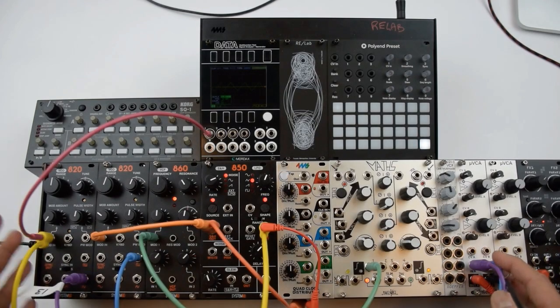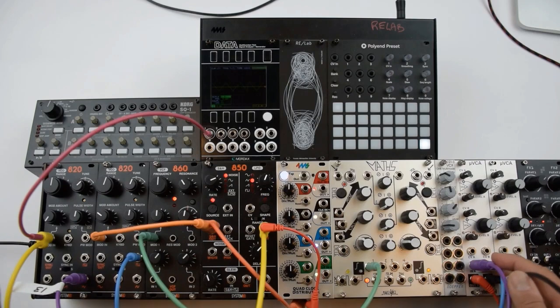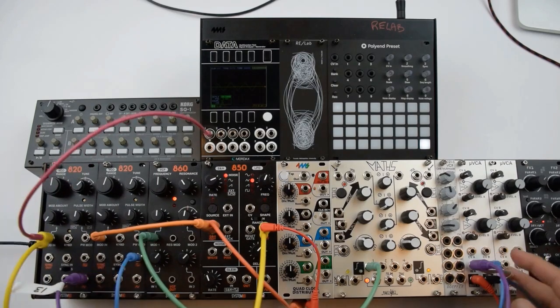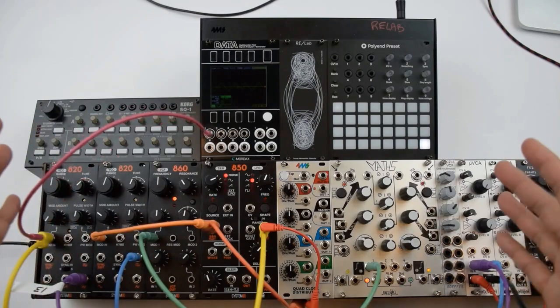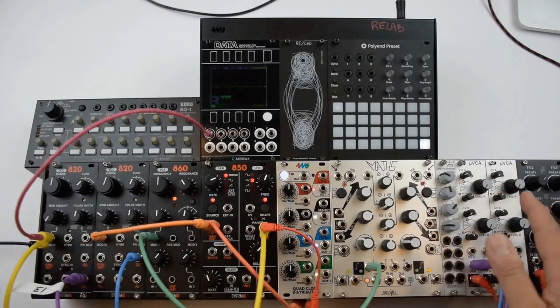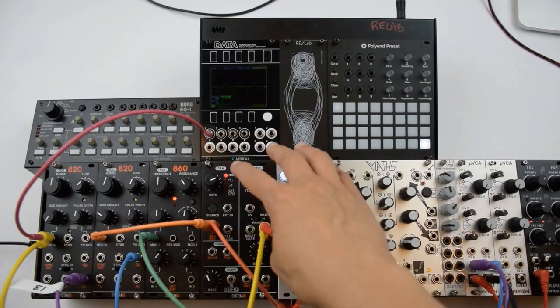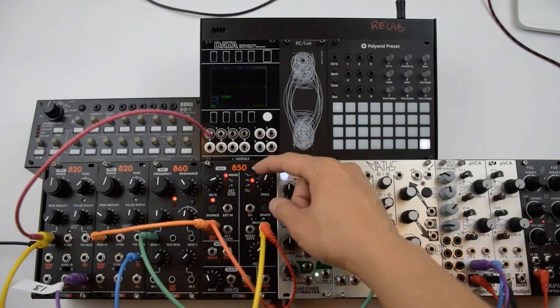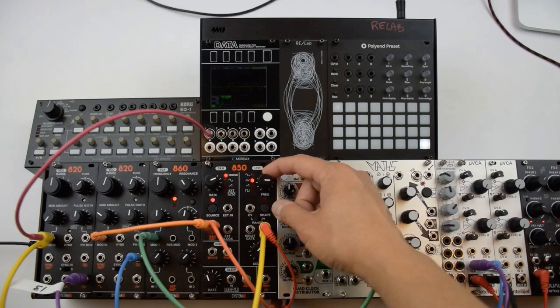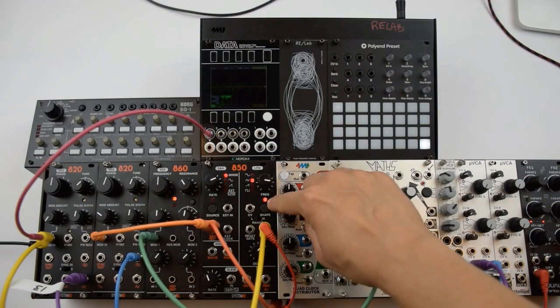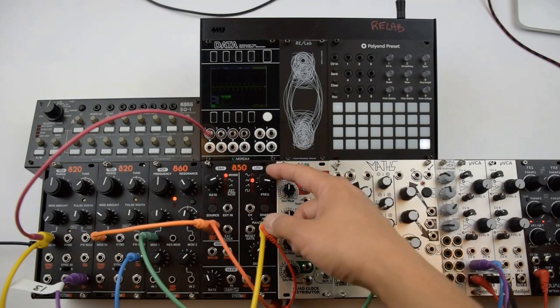An LFO, or a low-frequency oscillator, is simply an oscillator that runs very, very slow, below audio rate. So not at a frequency where we can perceive audible pitches. Everything we know about an oscillator still applies to the LFO, in terms of it outputting repeating waveforms and having those waveforms run at a steady rate set by a frequency or a rate control. So on the 850, here is our LFO section. It has a frequency control, and it even has a light that indicates how fast the waveform is oscillating.